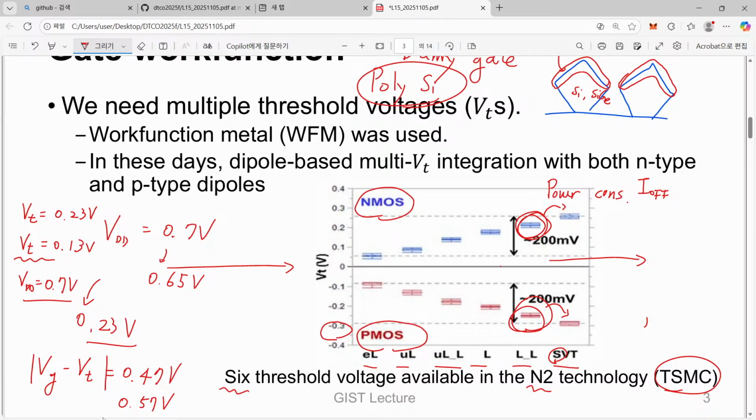And also if we go in this direction, then obviously this is more power consumption. So from the power consumption view, this is not a good direction, but at the same time we can severely increase the performance, because this just increases gate overdrive voltage. Please note that in many cases we don't have any further knob to change something in this family.